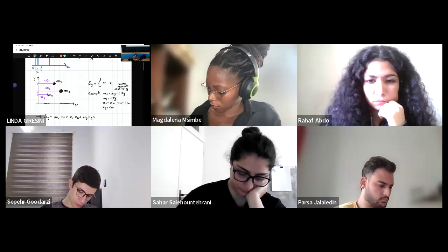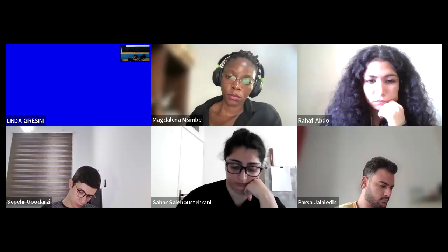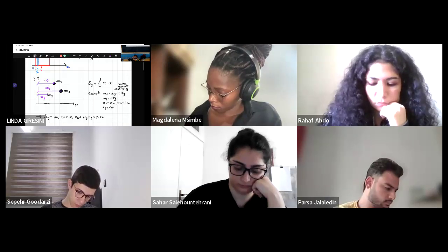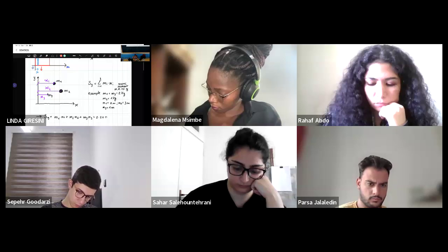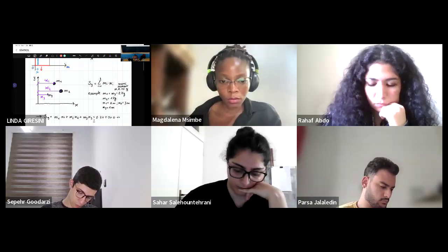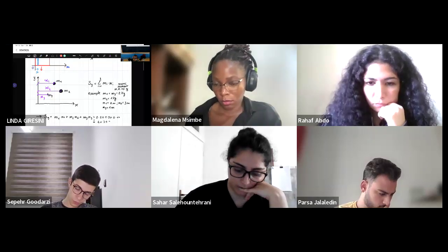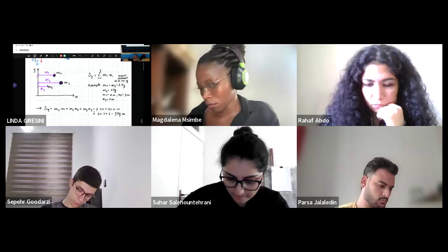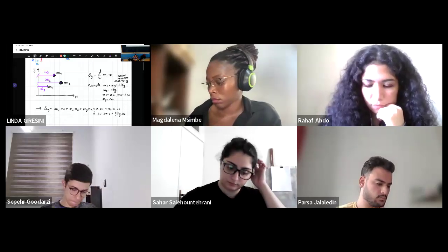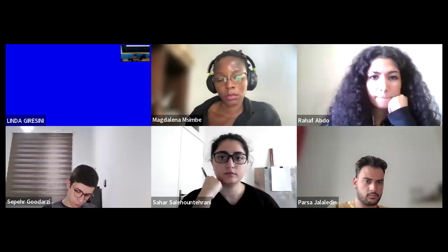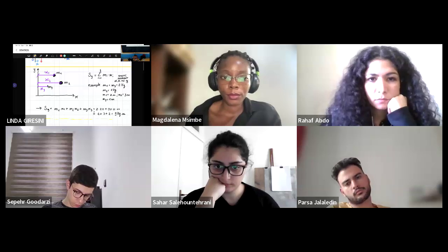So m1 is 2 kilos times x1 is 2 meters, plus m2 is 1 kilo times x2 is 3 meters, plus m3 is 2 kilos times 1 meter. In total, we'll have 4 plus 3 plus 2, so 9 kilograms times meters. And this is the static moment of the masses with respect to the y-axis.